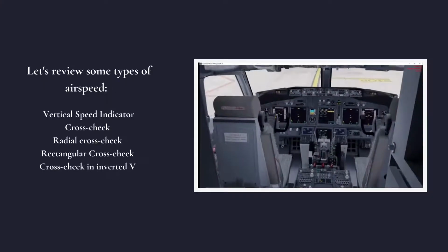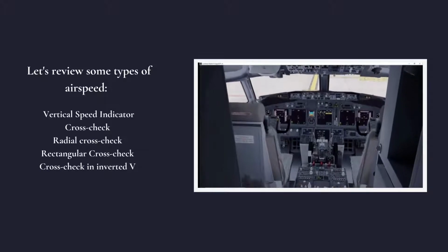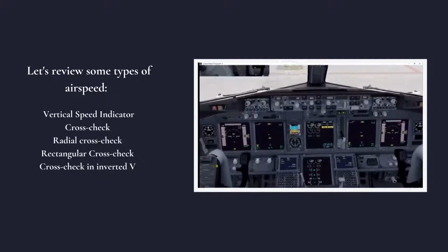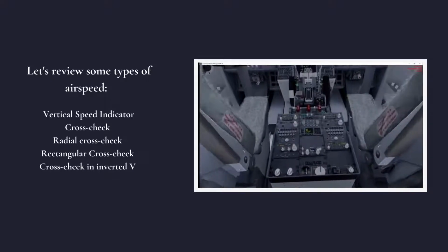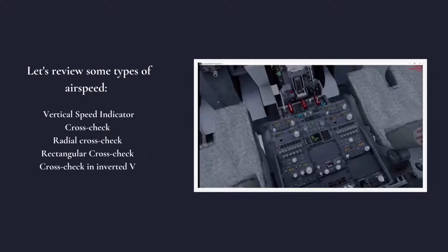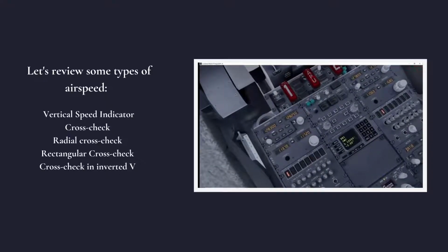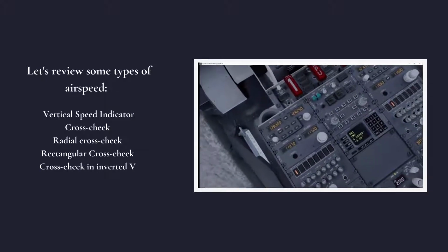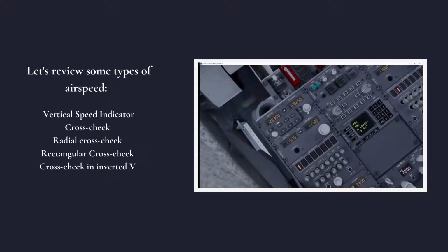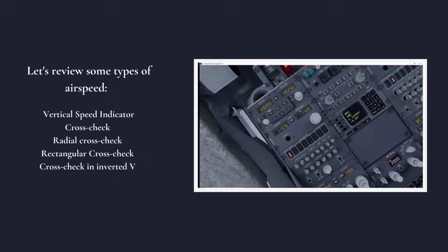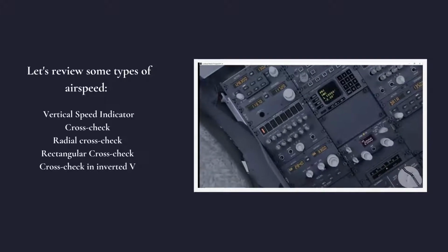Cross-check. It is the correct division of attention and interpretation of the flight instruments. Attention must be effectively divided between the instruments in such a way that they can be covered, determining the exact attitude of the aircraft, product of the different errors found during a flight, such as human error, instrument error, and variation of aircraft performance under different atmospheric and weight conditions.